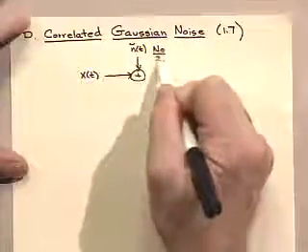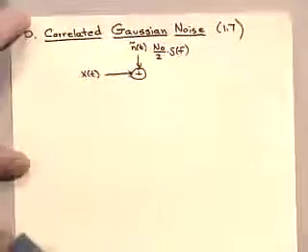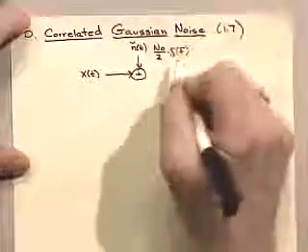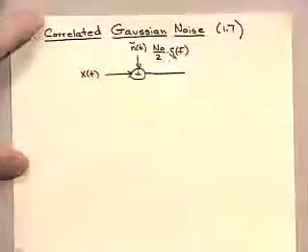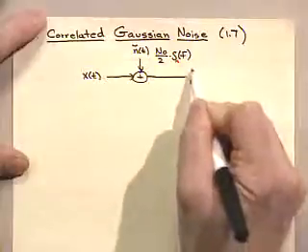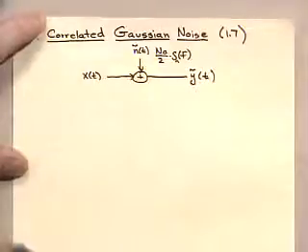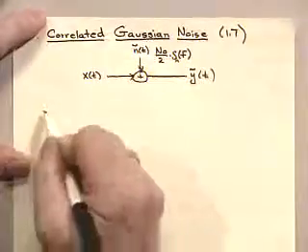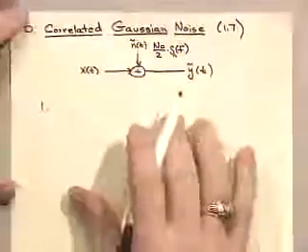We'll say it has n naught over 2 involved, but it's got some shaping also. So its power spectral density is n naught over 2 times some function, I'll call it s sub n of f. So it's a normalized power spectral density where I've divided out n naught over 2. And we'll call this output y tilde of t. Well, I submit that that is an intersymbol interference channel, even with no filtering in the channel. And it's there in disguise. How do I get there?